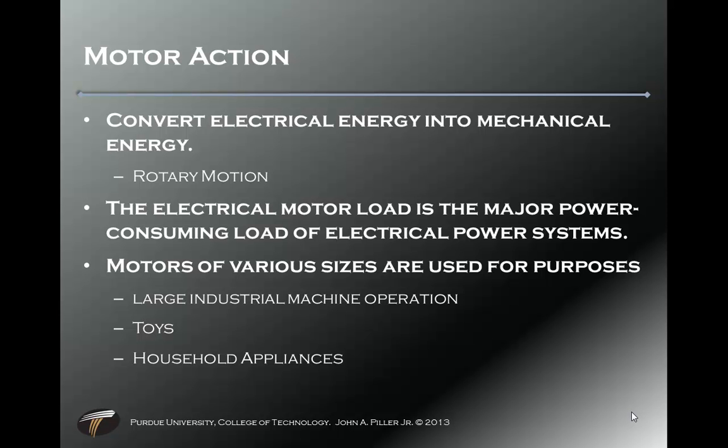We originally talked about generators. Motors again are rotating machines. Same construction as a generator, same principle. Faraday's law is causing motor action to happen, but instead of putting mechanical motion on the shaft to pull electrical energy out of a generator, we're putting electrical energy into the armature to pull mechanical motion off the shaft.